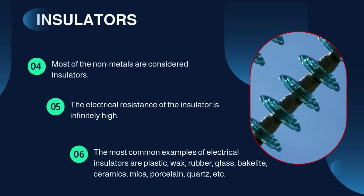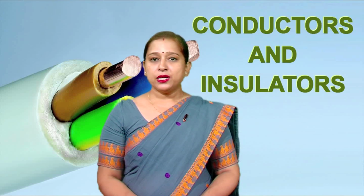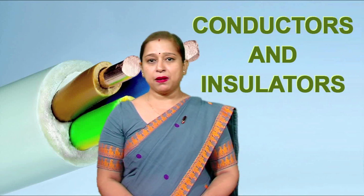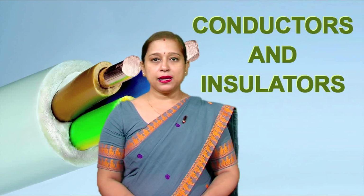Most of the non-metals are considered to be insulators. The most common examples of insulators are plastic, wax, rubber, glass, bakelite, ceramics, mica, porcelain, quartz, etc. The concept of valence band theory explains the behavior of electrical insulators. According to this theory, an insulator's valence band and conduction band are separated by a wide space known as the forbidden band. No electrons can travel up to the conduction band because the valence band is completely filled.